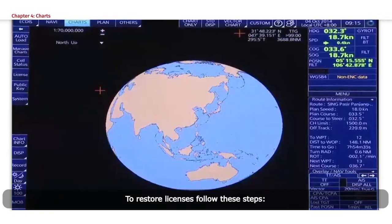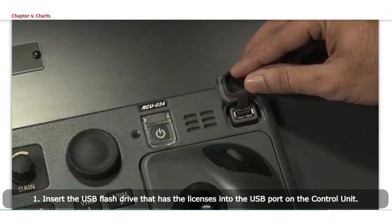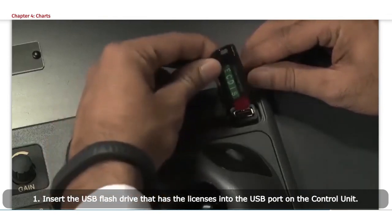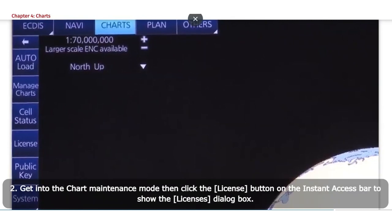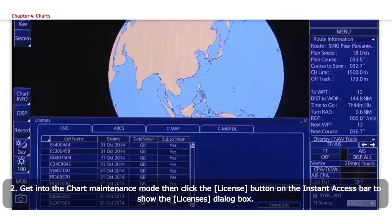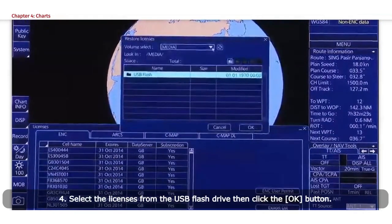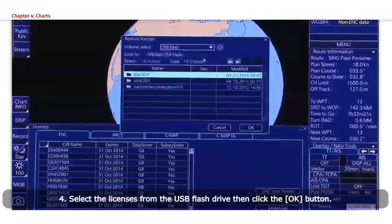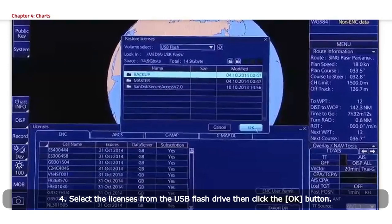To restore licenses, follow these steps. 1. Insert the USB flash drive that has the licenses into the USB port on the control unit. 2. Get into the chart maintenance mode, then click the License button on the Instant Access bar to show the Licenses dialog box. 3. Click the Restore Licenses button. 4. Select the licenses from the USB flash drive, then click the OK button.